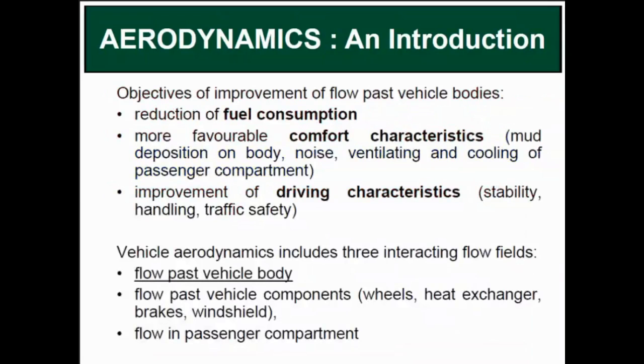The objective of why we need to study the aerodynamics of the vehicle is that we need to improve the flow past the vehicle bodies, so that we can reduce the fuel consumption, make it more comfortable for the driver, such as reducing the noise, and study the ventilation or cooling effect of the passenger compartment, and also reduce the mud deposition on the vehicle body.